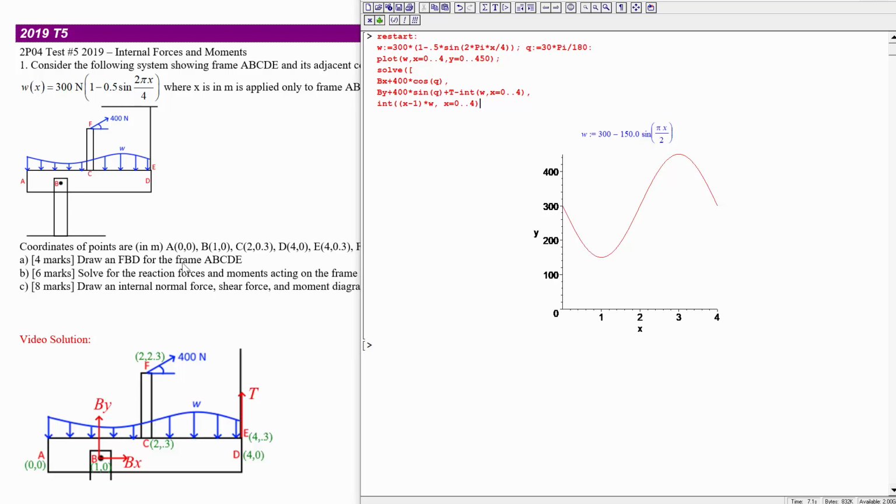Over the whole thing. So let's see, do we have to check the right hand rule? Right, we have to see if this is doing the torque in the right direction. Normally we want the torque to be out of the page for positive, and this would be creating a torque into the page, rotating the other way in the clockwise direction. So we actually want to multiply that distance by negative w. Okay, so that'll be the torque produced by the distributed load.